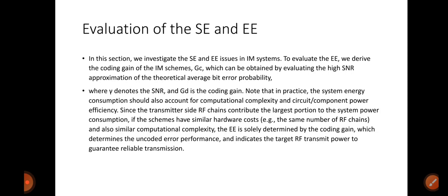If the schemes have similar hardware costs and also similar computational complexity, the EE is solely determined by the coding gain, which determines the uncoded error performance and indicates the target RF transmit power to guarantee reliable transmissions.